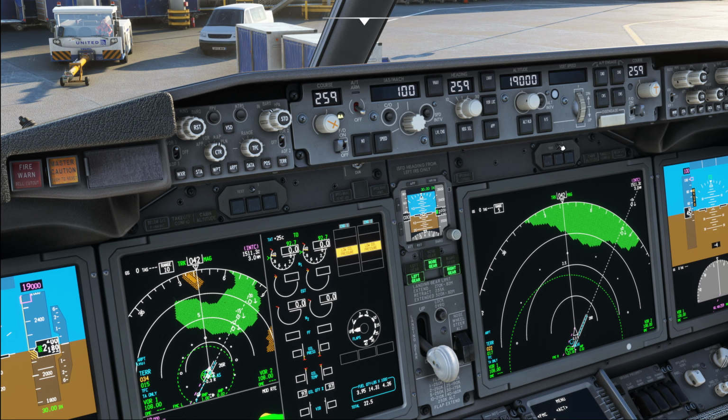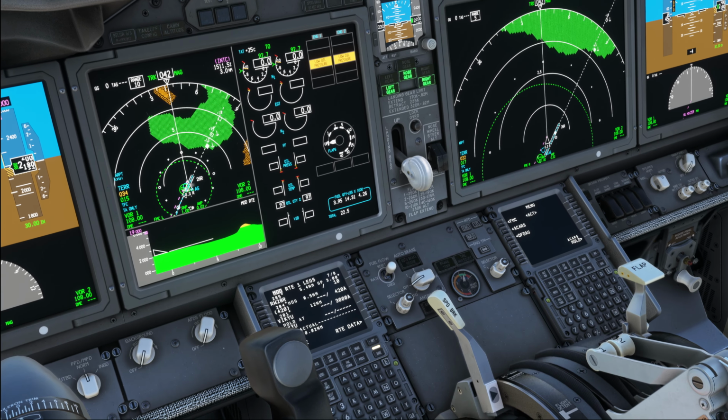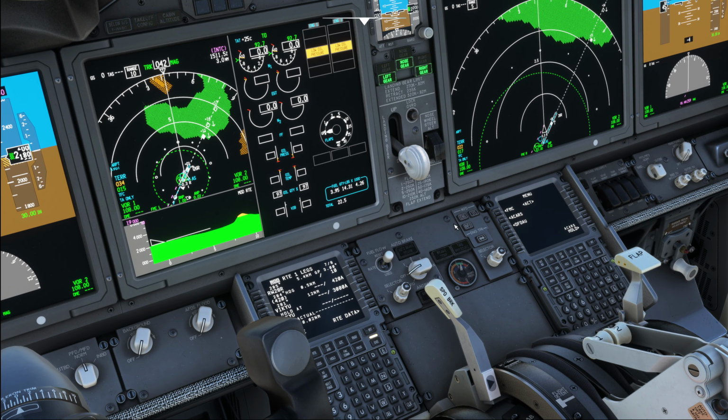So moving on to the right hand side, we are going to check the indicator on the right hand side, and moving further down we make sure that the nose wheel's alternate steering switch is guarded, which leads us down to the panel down here. So, fuel flow, reset, auto brake, RTO. Make sure that the disarm light first illuminates, then extinguishes. Check that we have brake pressure.